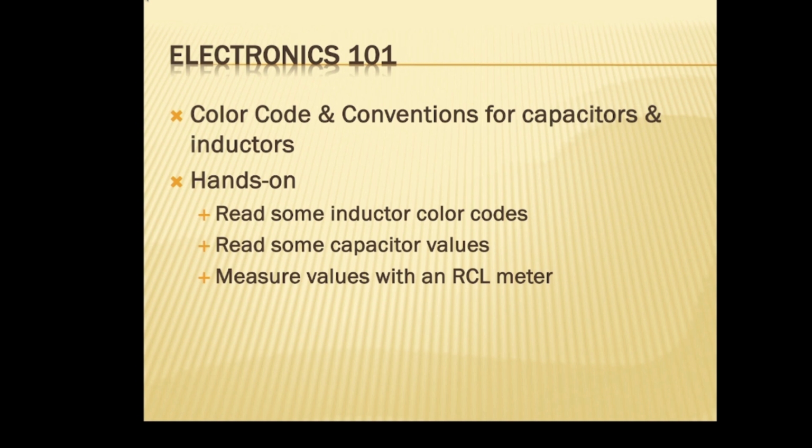Okay, it says it has very low resistance, which is not unusual for inductors. So we tap the scroll button and go to the next reading. It has 0.2 or 2/10 of an ohm of DC resistance, and its value is 7.3 microhenries. Does that come out close to what the markings say? I don't know, I didn't check the markings yet. I was checking with the other meter.